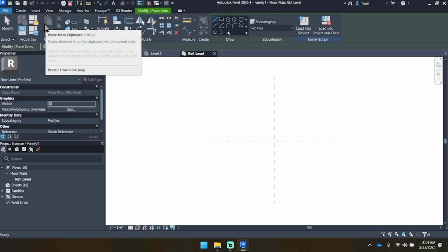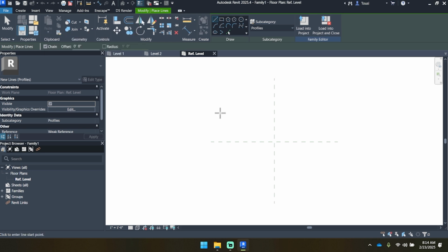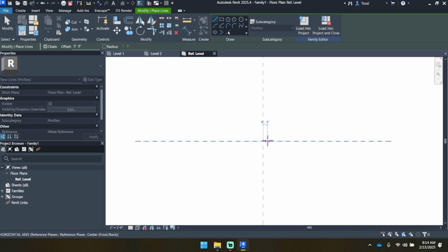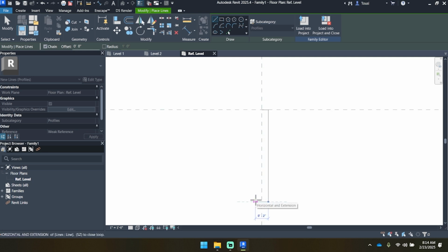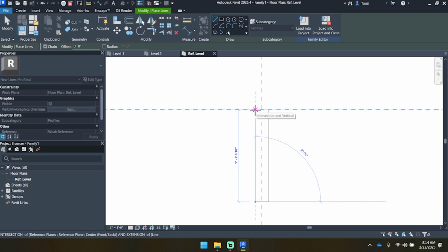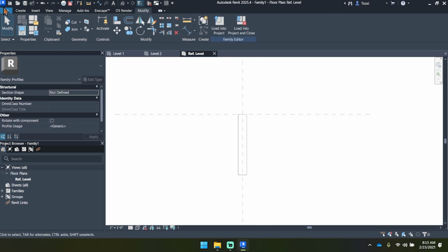And we're going to draw the 4 lines as we see on page 8-47 on the bottom right under figure 8-3.13. So I'm going to start at the top intersection location. I'm going to go over an inch. I'm going to come down 1 foot, 2 3/16 of an inch. I'm going to go over 2 inches as that'll be the total width. Come back up, matching up with that horizontal line, and then coming over. And now let's save it.